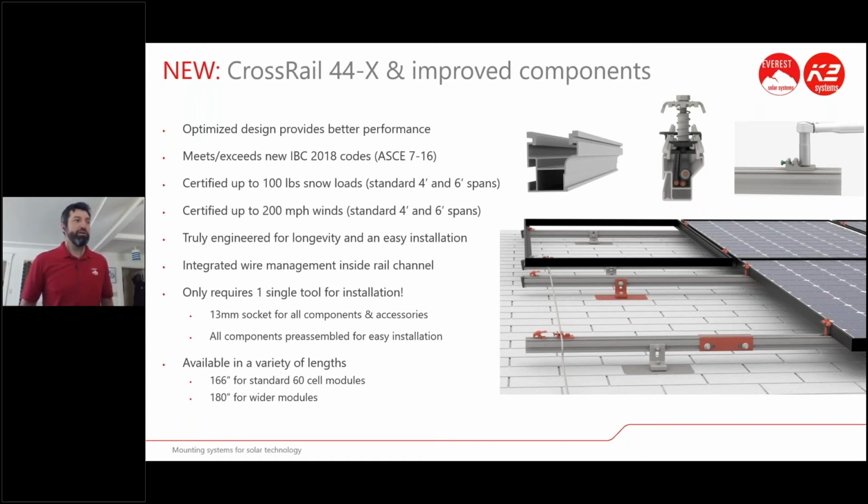It's certified up to 100-pound snow loads. And again, this is generalizing 4-foot, 6-foot spans, basically what you're already doing in most cases. If you're doing 4-foot spans on the East Coast, and you're using our 48X, chances are you could probably transition to this 44X seamlessly. You obviously need to check and make sure. There are certain scenarios where you might have huge snow loads, and you might want to stick with 48X or maybe 48XL if that's what you're using. But 44 does perform very well, and you can do 4-foot, 6-foot spans, regionally based. And again, it is certified up to 100-pound snow loads, and 200-mile-per-hour winds.